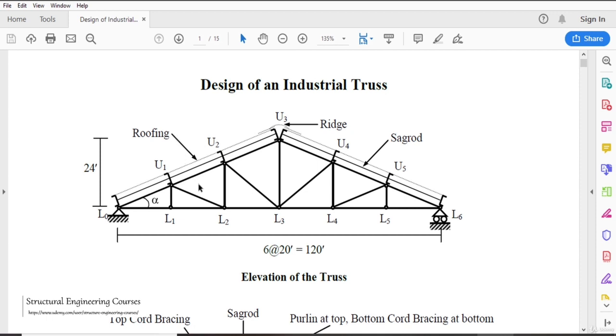So what we need to do is multiply the spacing between the 2 purlins, that is the effective span area. I am repeating the term effective span area. This purlin shall contribute to resist the loading from 50% on this area and 50% on this area. When we cross this 50% path here, after that the contribution comes from the next purlin. So this purlin shall resist the loading on this 50% area and this 50% area. This is a very important concept that you do need to understand.